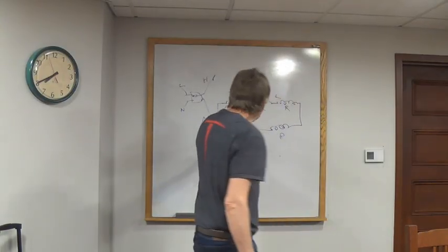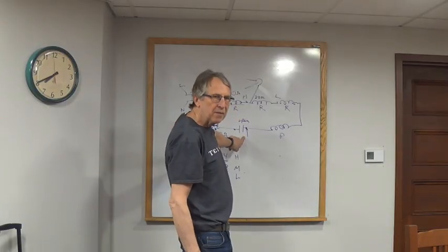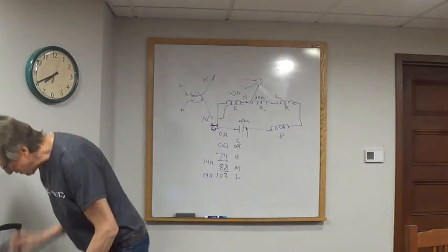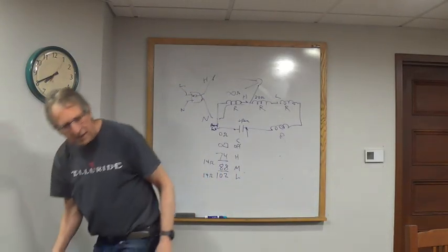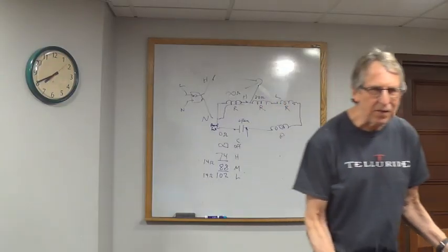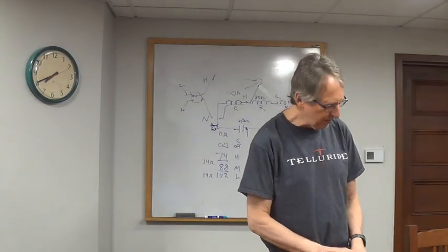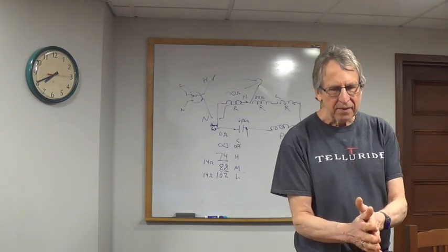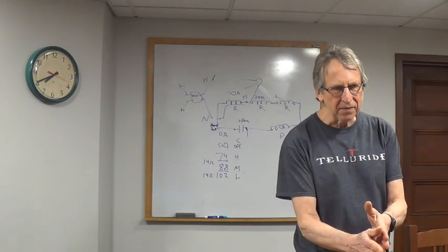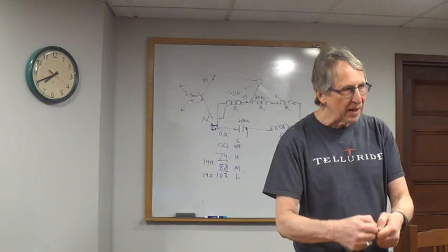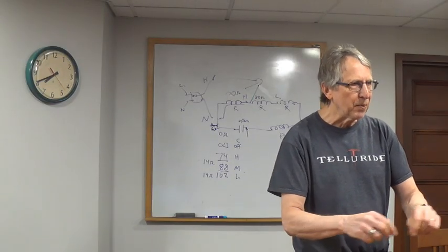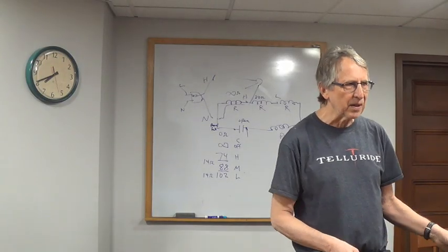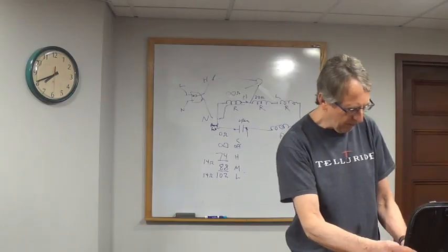Remember you said, well, how do you get to the capacitor? Because there's no terminal for the capacitor, I'll show you how you do it. This is the capacitor. You guys can do this because it's my motor, but if you're doing this for somebody's fan that you're fixing, you probably actually want to cut the wires, and then be prepared to reassemble them either by soldering and putting heat shrink, or wire nuts or something like that.